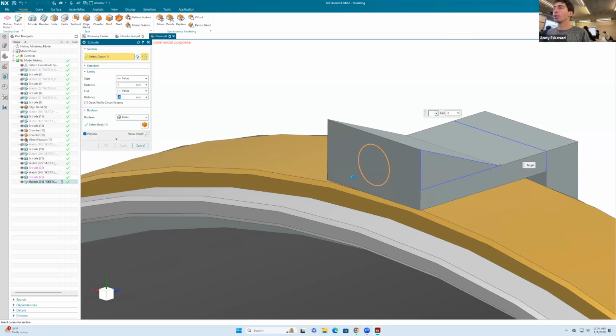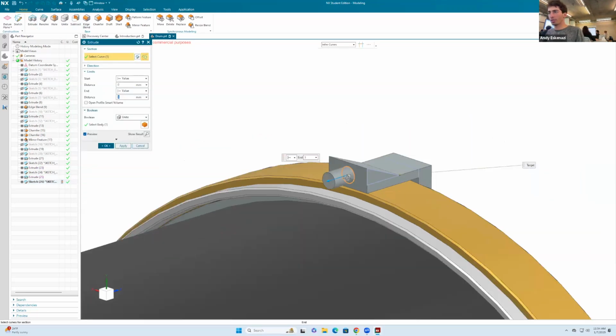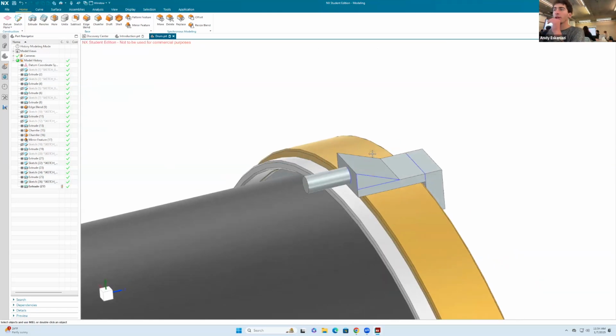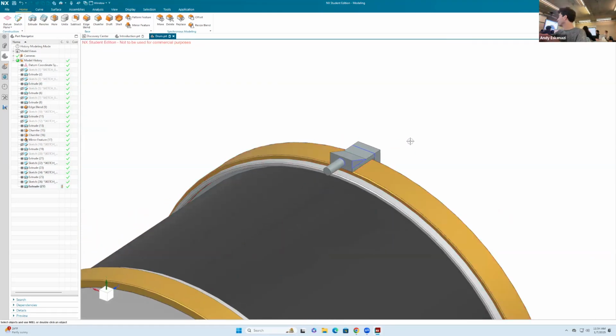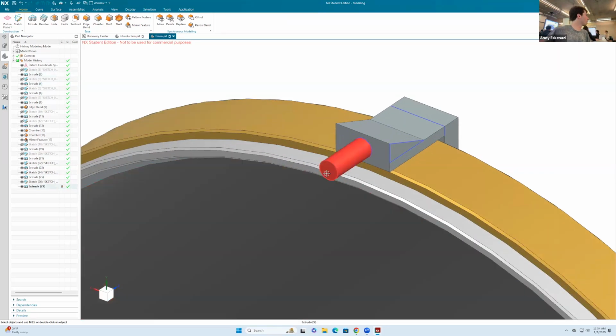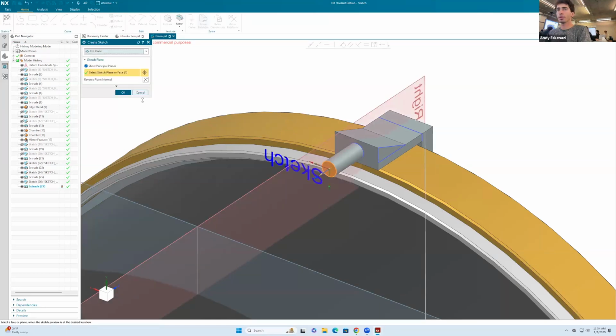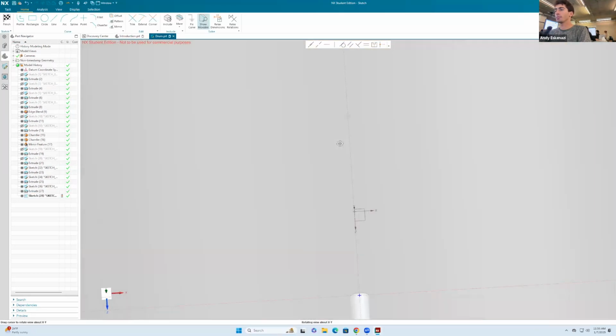And then let's go here to an extrusion. Let's extrude by 3. Maybe actually, we do a little bit more. Let's do 5. I'll say okay. So now we're starting to build that bar. And I can make a little knob in there. That's gonna be super simple to do. I go here to, again, sketch. Face, I'll say okay.